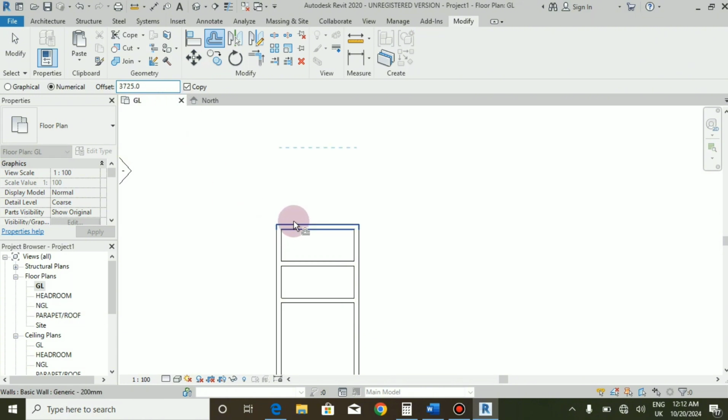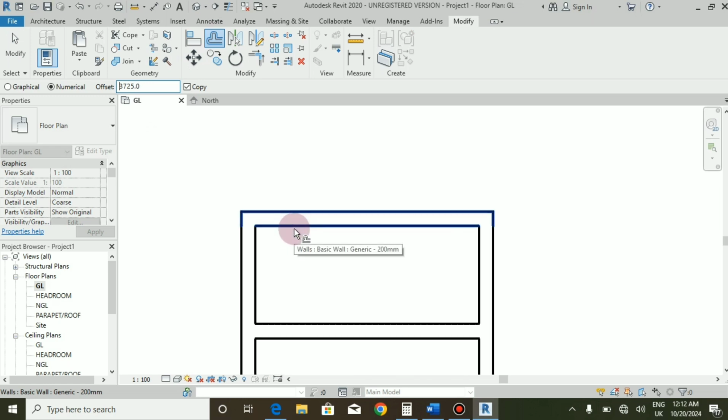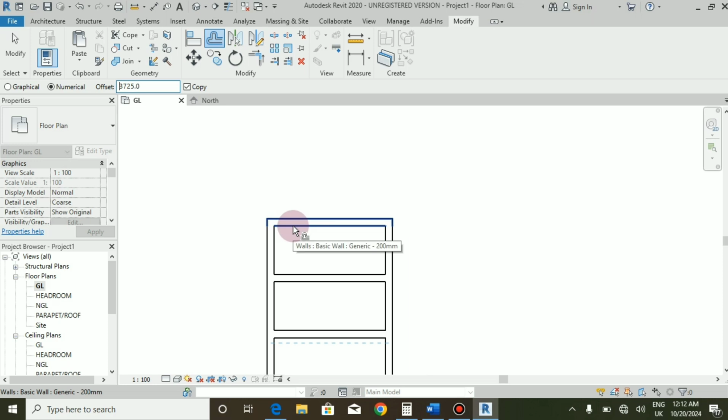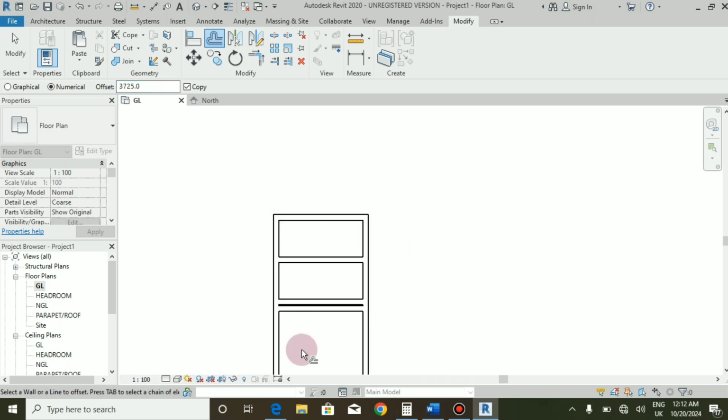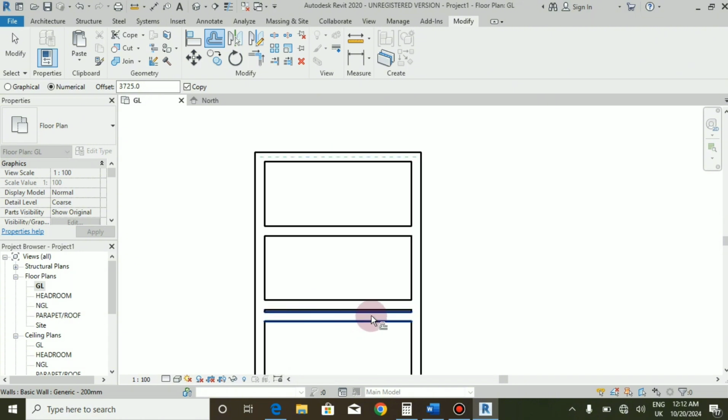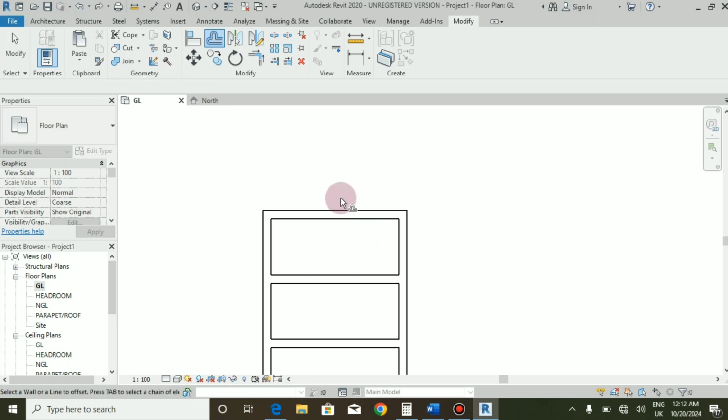So I click the outer. If I click the inner, you see, if I click the inner aspect, my wall will be here at a very, can you see a very blue line here? So let me click it first. Can you see that it's created the wall here? Why? Because I clicked in. So I have to press Ctrl Z to undo what I've done. So this is Ctrl Z, and then it undoes what I've done, and then the command is still there, and then the distance is also there.